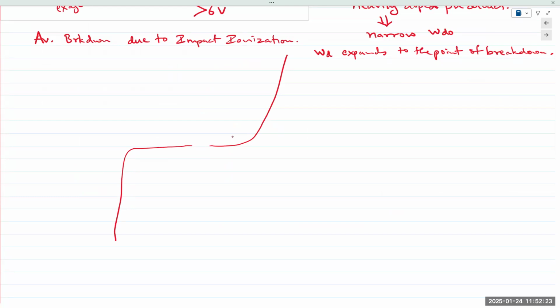When you plot the forward characteristics, you'll be able to see the slope visually, even without looking at just numbers. With the reverse bias, it's almost a vertical line. But that's an excellent point. If it remained constant, we could potentially use it. But the forward bias voltage drop is a function of the material and the doping, so it's going to stay near constant at 0.6, 0.7 volts.